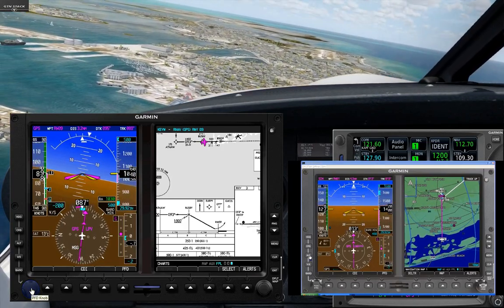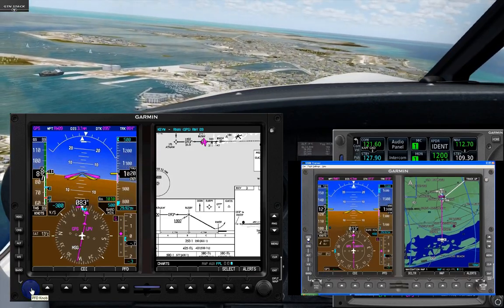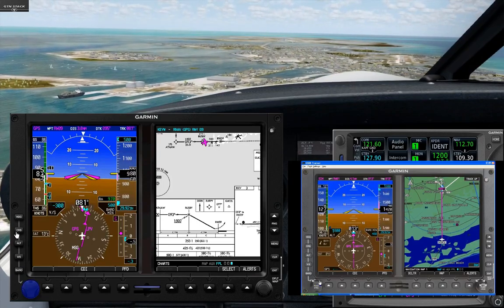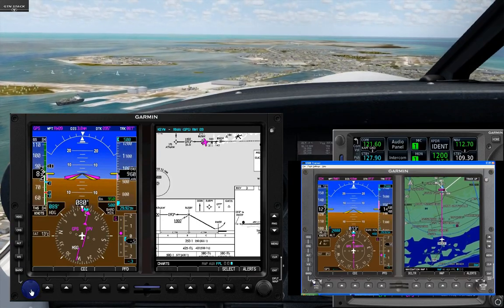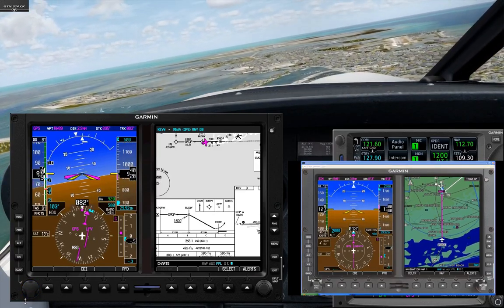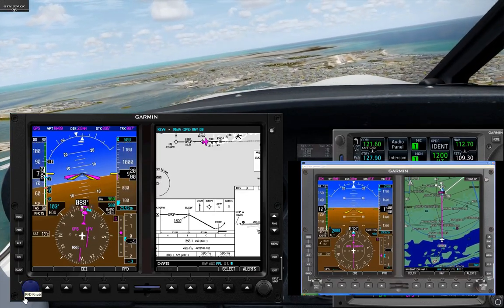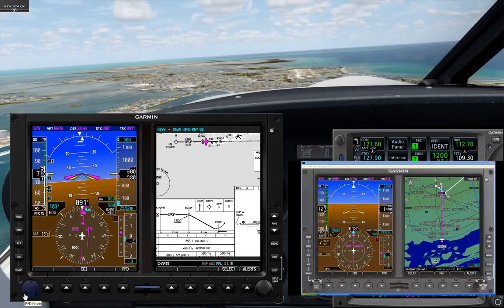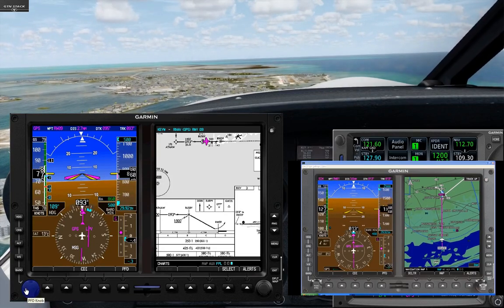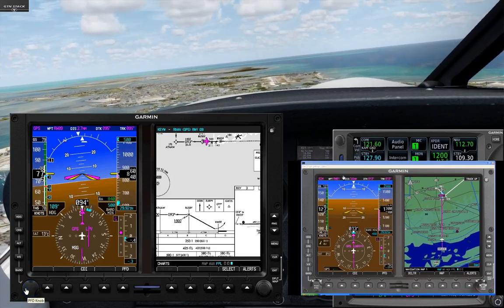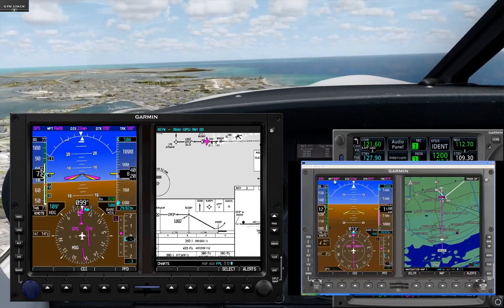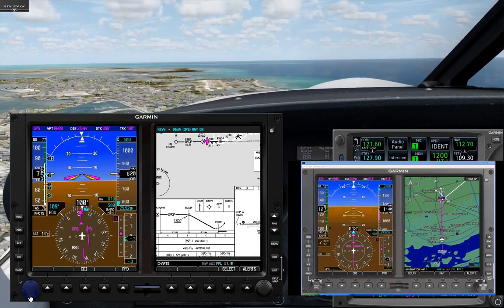As well as we would want to reselect altitude. We can select heading to sync it to our current heading, reselect altitude, pre-select the missed approach altitude so it's available to us when needed, and we're going to keep descending down to the minimum descent altitude for this approach. And we have the same presentational information right in front of us. We see the next waypoint is runway 1.